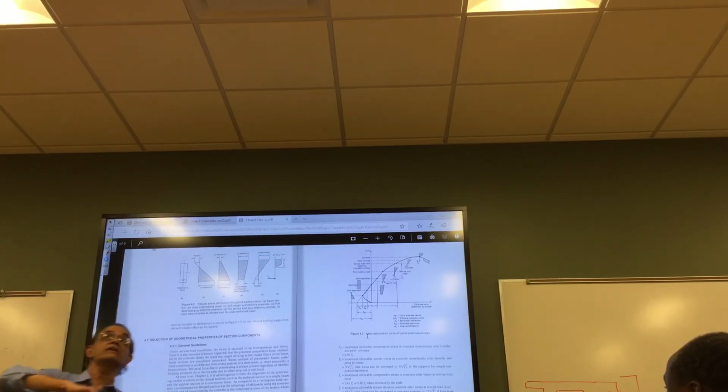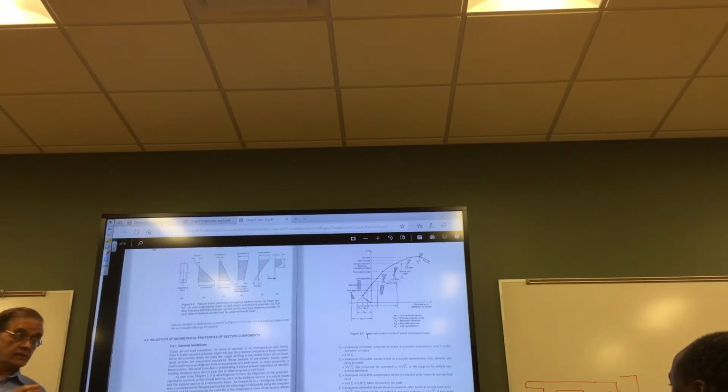That's what we do a lot in steel design. We design a steel girder. You find out how much deflection you expect for the service load, and you ask, what is my sustained load? Typically, the dead load that I'm pretty sure will stay there. Under the dead load, I would like to have a flat or slightly cambered-down beam, but not by many times for a longer span.